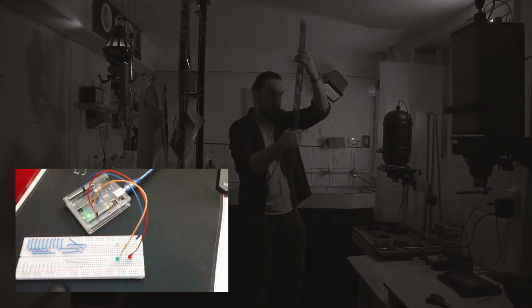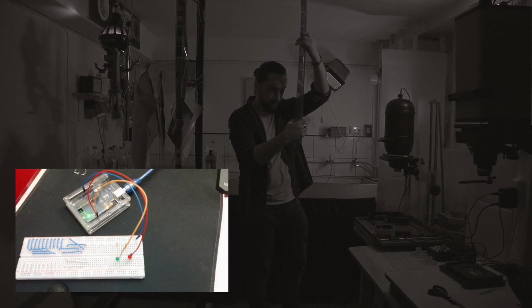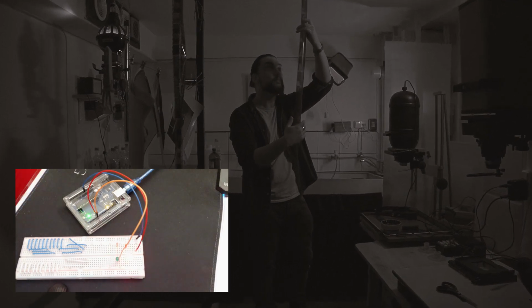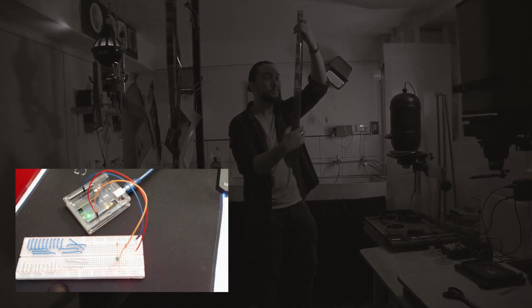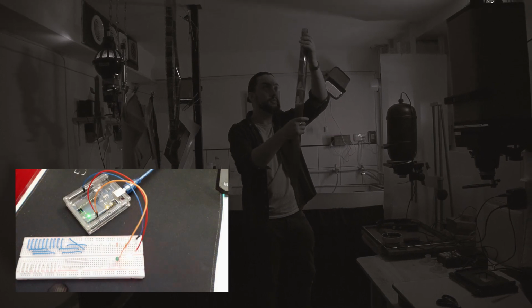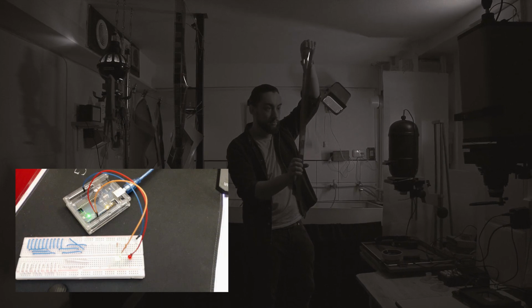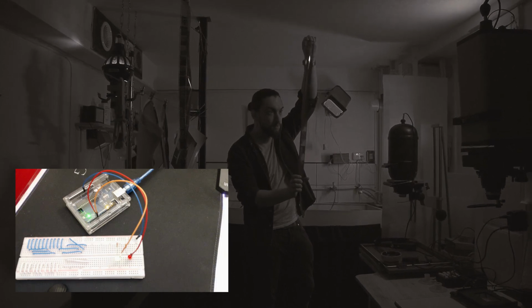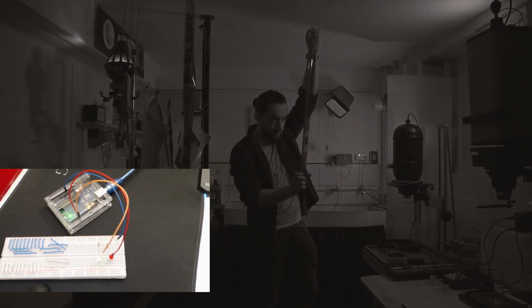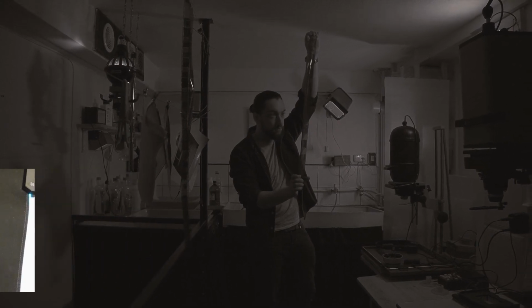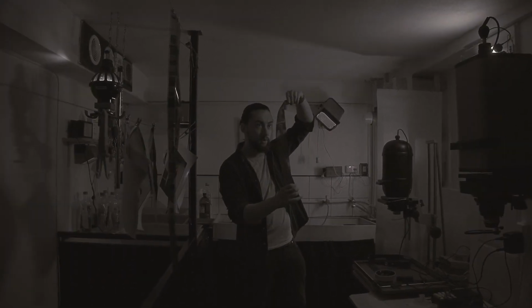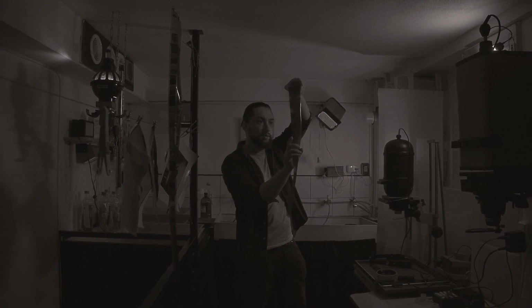The main task will be the development of an electronic circuit to control the operation of two LEDs, red and green. A red LED on indicates that the darkroom is busy and the photographer is working. If it lights up green, the darkroom is free and it can be entered. The operation of the LEDs is controlled by commands given from the computer via the serial monitor to the Arduino microcontroller.